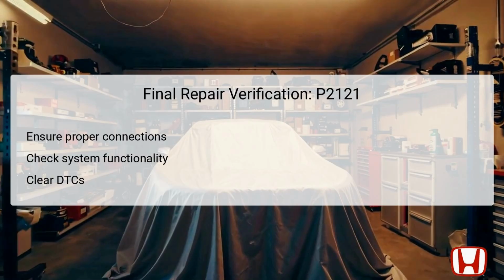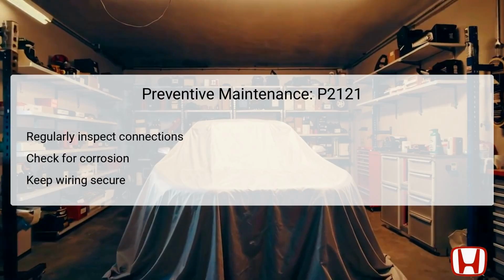Finally, clear any DTCs using the HDS to reset the system, allowing it to recheck all parameters before returning the vehicle to the owner. To prevent the recurrence of DTC P2121, maintaining the integrity of the wiring and connections associated with the APP sensor is crucial.